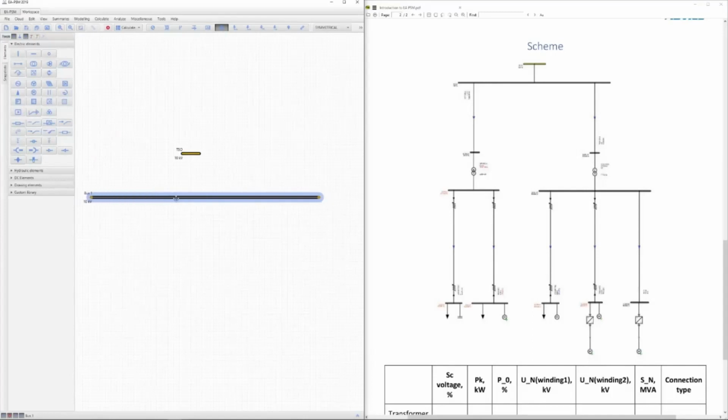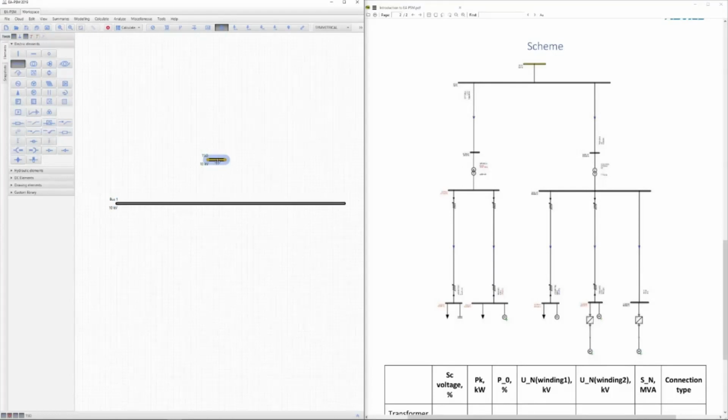So let's now expand this. Then we're gonna connect our first infinite bus bar to the secondary point. But I must mention that when adding cables, it is very, very important to know which way you're placing the cable. You have to press on the first bus bar, that is your beginning, and the second one, that is your end. If you input it correctly, then all your data will not be reversed and some calculations will not interfere.